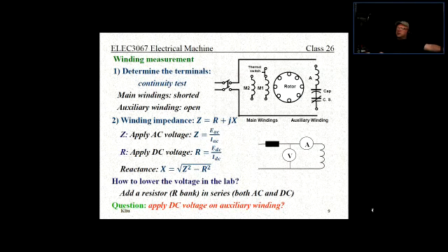All right. Rodrigo says, but with the three-phase, it is self-starting. Yes, the three-phase induction motor is self-starting, because the three phases are arranged 120 degrees out of phase with each other, which, when we apply three phases, creates the revolving magnetic field. So in a three-phase, we have the luxury of having the revolving magnetic field right away.